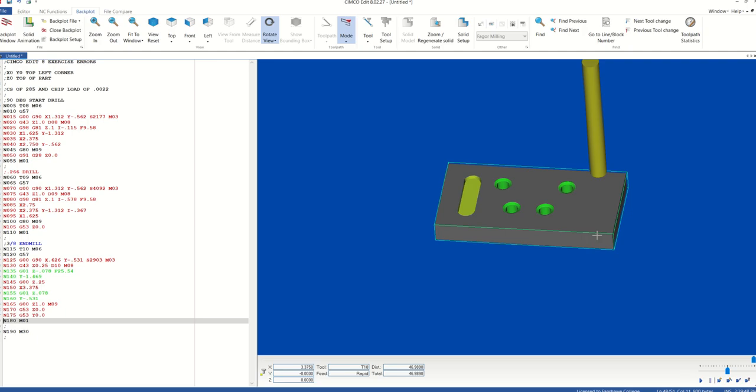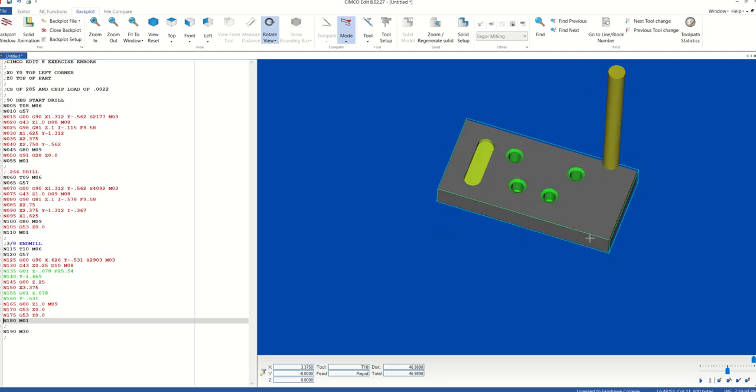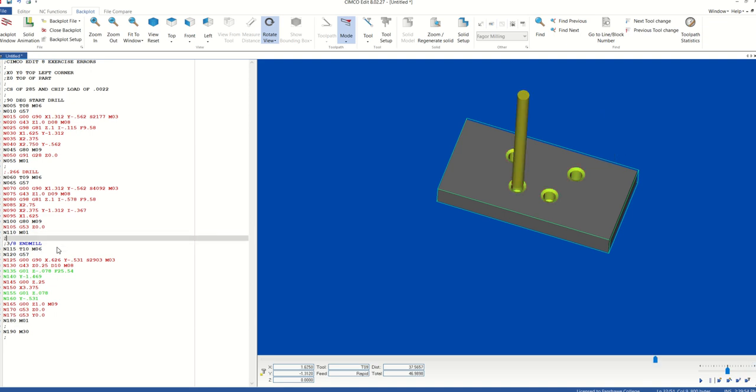So what I need to do is, again, look at my code and figure out why that is like that. The easiest thing I can do is once again come through and individually go through each command line and see where my problem is. So I move into position, I come a 1/4 inch above the top surface of my workpiece, I turn my coolant on, I'm feeding down, and again, because this is a G01, we know we're using a simple motion, so I'm feeding into my part Z minus 0.078.